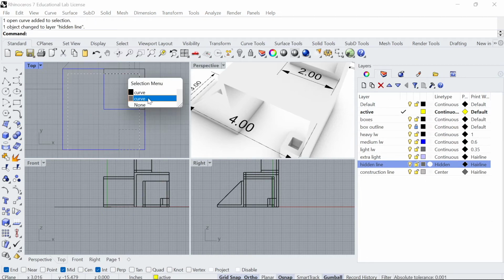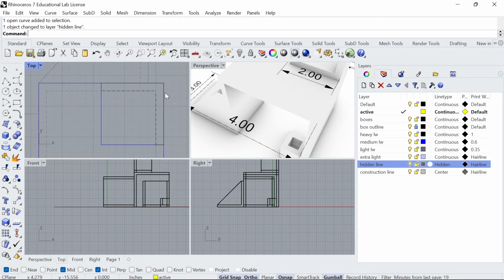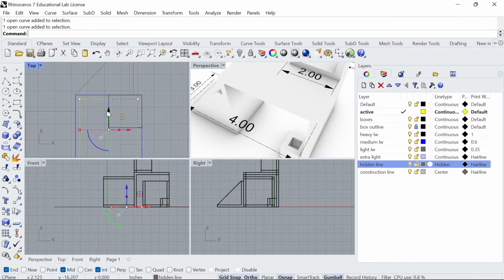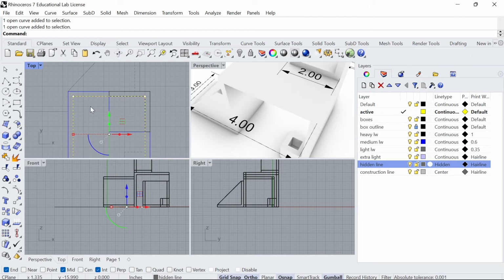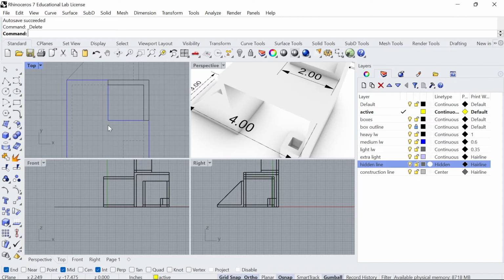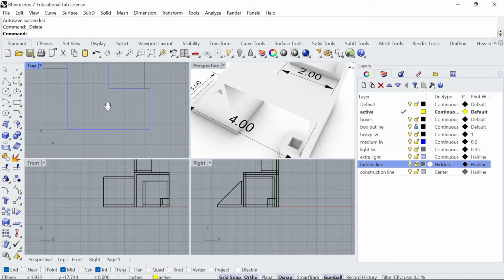Okay, and what you'll notice is that you have an overlap of lines. This thicker line, which is a line for the 2-inch cube, is going to show on top of the hidden line, so you probably don't have to worry about it. If I'm being picky, I'll probably be trimming this hidden line off, which you probably should. So I'm going to select this, select split, and split it right at this edge right here, like that. And then I'll select the hidden line right here. So this is the dashed hidden line. We don't need it in orthographic. Now you just have two lines on top of each other, so I'm just going to go ahead and delete it. There's no need to do that. And that was a result of the process in which I'm drawing the thing in Rhino. You just have to be aware of these things. There are obviously many ways of doing it. Okay, so moving on to the next thing.